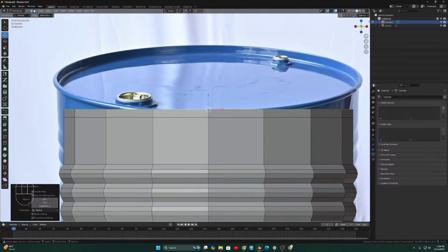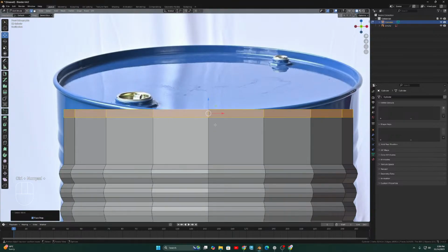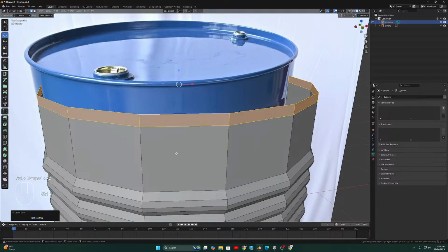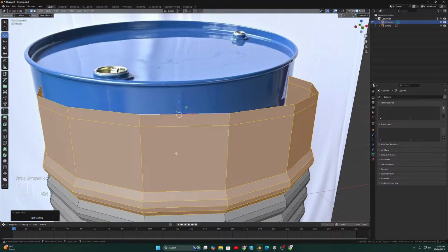What we can do, let's do one thing. Click this. I made a selection by pressing Ctrl plus. Okay, how you can grow selection, let's learn this as well. Select this loop completely, alt click, then Control plus. Now keep clicking Control plus, it will keep adding the next loop.